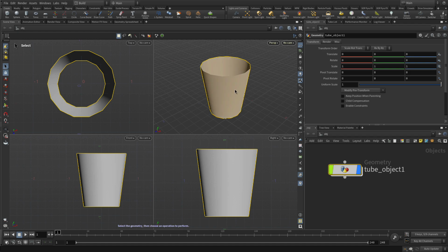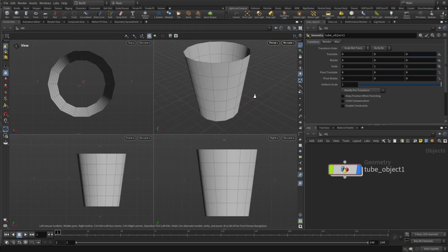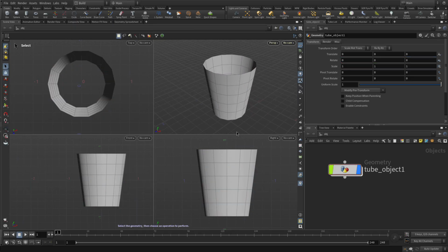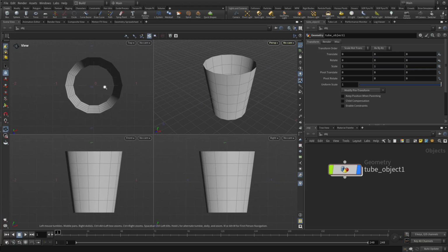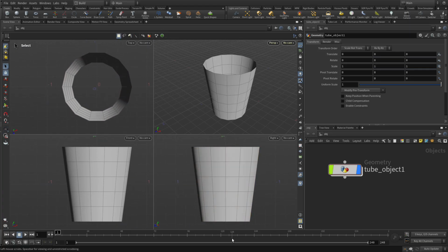And if we want to, we can go into here and press V, Shading, Smooth Wire Shaded. Currently that only does the one view there. If we click up here and go Smooth Wired Shaded, we'll get all 4. And that just allows us to see the topology in case we want to work with it as we're making decisions. Now another option here is to go in and link the ortho view. Now if we make view changes in one of these, the other orthographic views all follow suit, so that keeps a relationship between those 3.